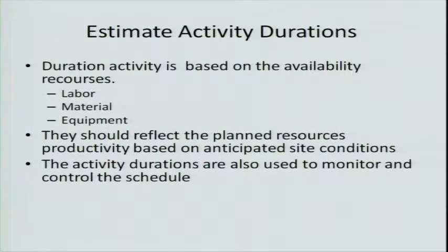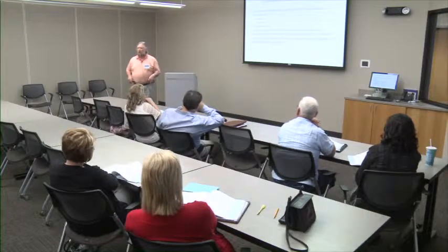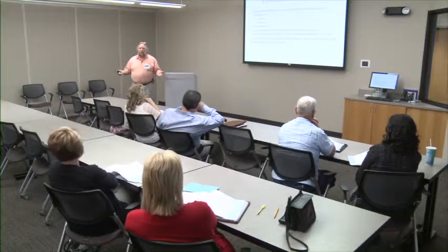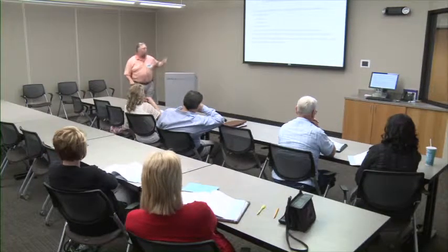Okay? So we estimate activity duration. The duration of how long it's going to take us to do something is going to be based on the labor, the material, and the equipment that is involved in doing it. Can we get all those things there at the same time? If we want to move 100,000 yards of dirt and we're going to do it with wheelbarrows, we're going to need a whole bunch of laborers and a whole bunch of wheelbarrows, because we know how much the material is and the time frame involved. Now we can estimate how long, because we can move a wheelbarrow 20 or 30 feet in an hour, depending on how big the wheelbarrow is. But it's an exaggeration.